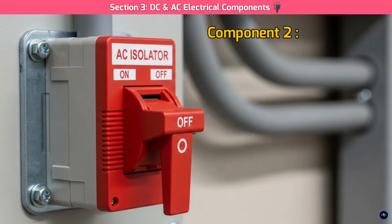Component 2, the AC isolator. Next, we have the AC isolator. This is your manual emergency switch. It's a physical disconnect that lets you completely shut down the solar inverter from the grid for maintenance or in an emergency. Its specifications are straightforward.